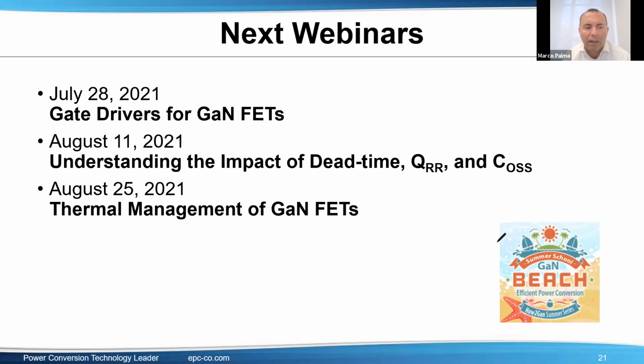And the other most important thing is the TO220 package, I think, is the highest inductance package you can find. And then you jeopardize completely what I just showed today. What you get is a lot of ringing, a lot of power dissipation. You will get no advantage at all. Here we're talking about very fast transitions that you have to manage in the right way to avoid any EMI, EMC, and to get the advantage of the fast switching. So you have to minimize the inductance to the bare minimum, and that means the package has to be chip